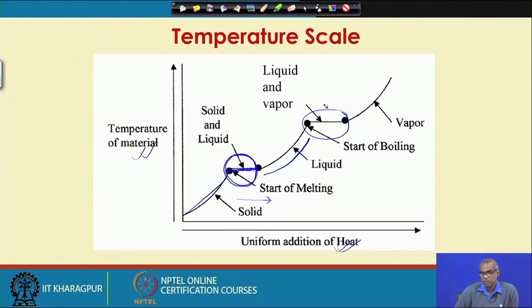Again you note the temperature does not change here upon supply of heat. So, this is another condition where a liquid and vapor state will be in equilibrium and can be considered as a fixed point or standard for temperature measurement. When liquid becomes completely vapor, again the vapor shows increase in temperature with supply of heat.